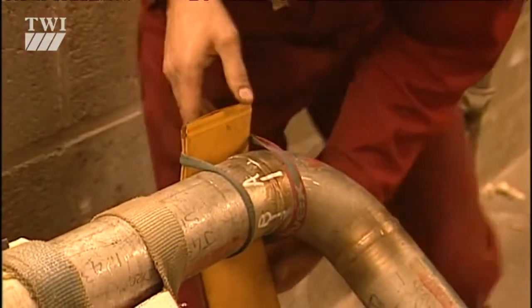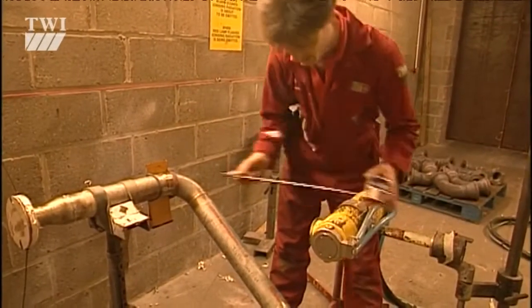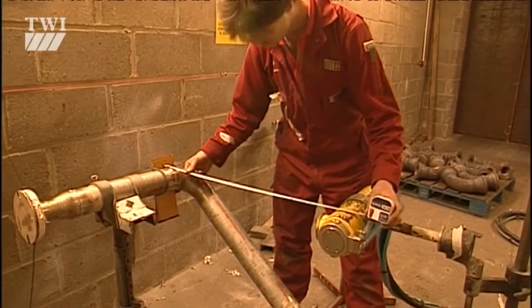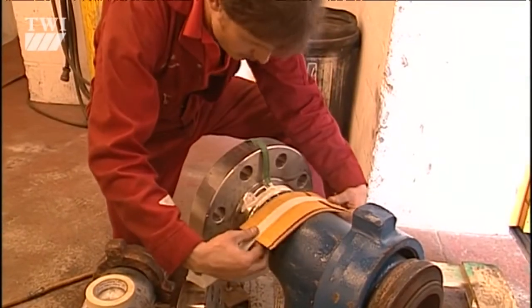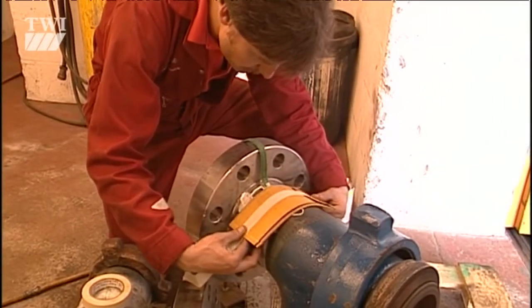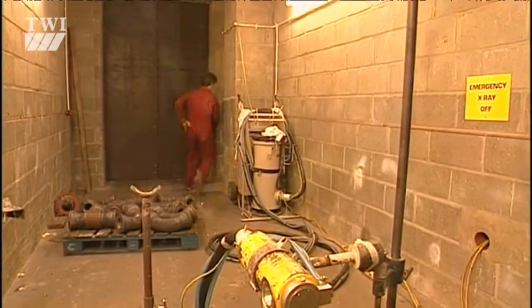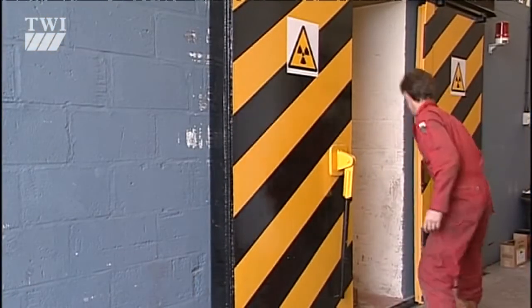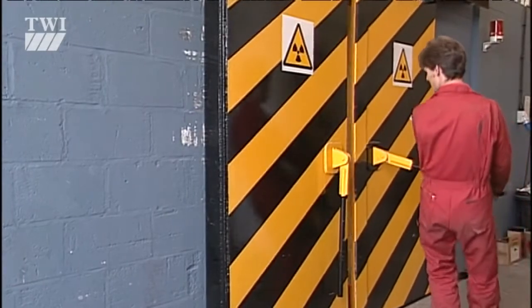For radiographic inspection, there's no need for surface preparation before testing. But you do need to have access to both sides of the component. The film, which is highly sensitive to X-rays, is placed on one side, and the X-ray source is carefully located opposite. The X-rays pass through the component and create a latent image on the film on the other side. Any volumetric flaws or discontinuities in the component allow more of the radiation onto the film, and this creates a darker image on the radiograph.